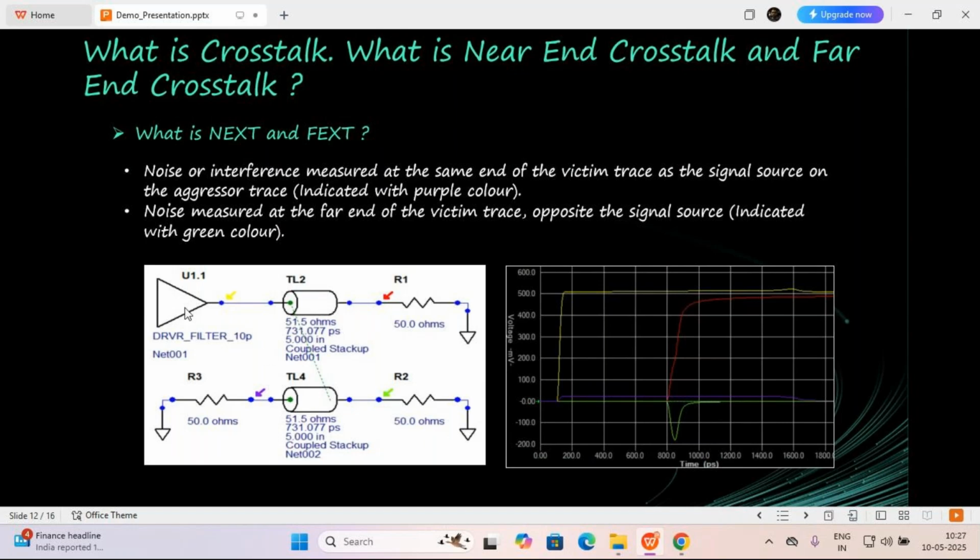Now, as this pointer shows, you can see the yellow arrows and red arrows on the graph also. Wherever the red is, that is the signal over there. Here we can understand two things, including the propagation delay. Since both transmission lines are the same, I have to give a 50 ohm termination, because in the tool you cannot short the transmission line to 0 ohm.